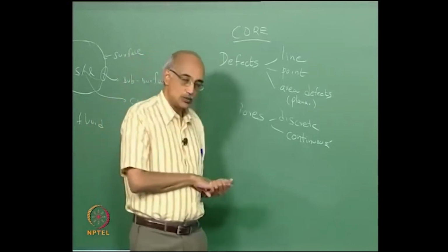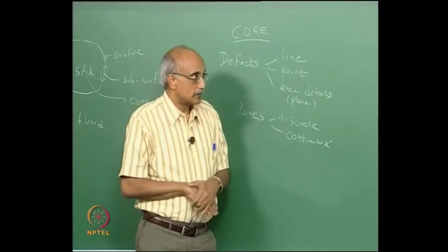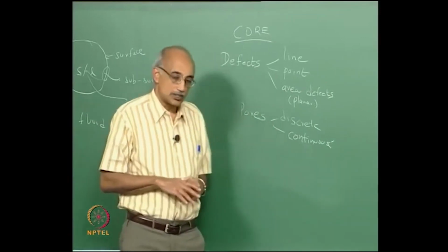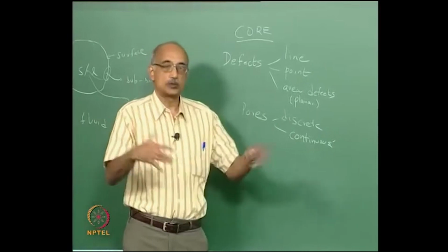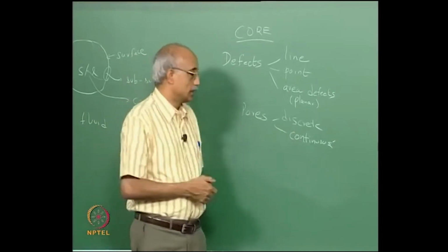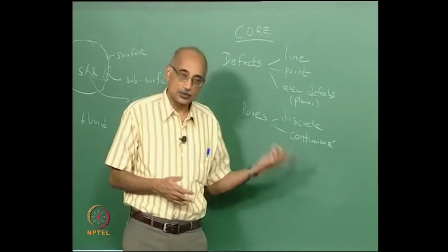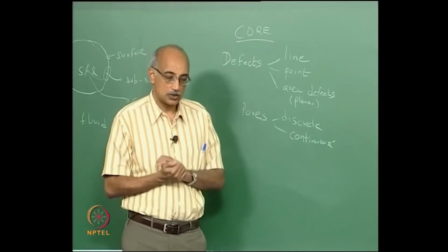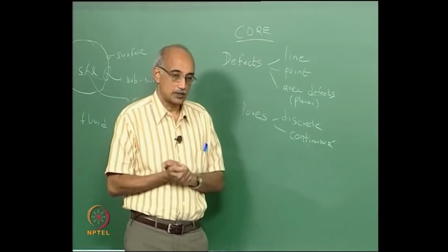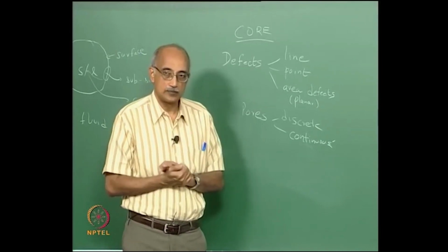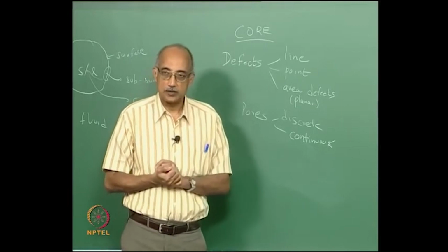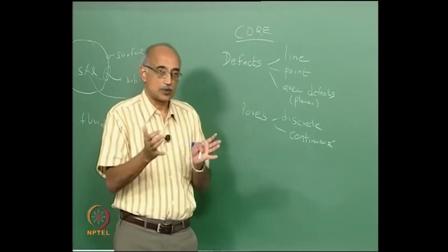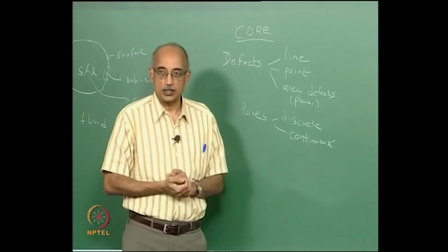However, when you have continuous pores, it's just like the interconnected capillaries that we saw earlier. It essentially provides a path throughout the entire particle for any of the harmful effects associated with the porosity to propagate. So as far as possible, you try to obtain a material that has zero porosity, which is very difficult to achieve, or your fallback option is to discretize the porosity so that they are not continuous in nature.